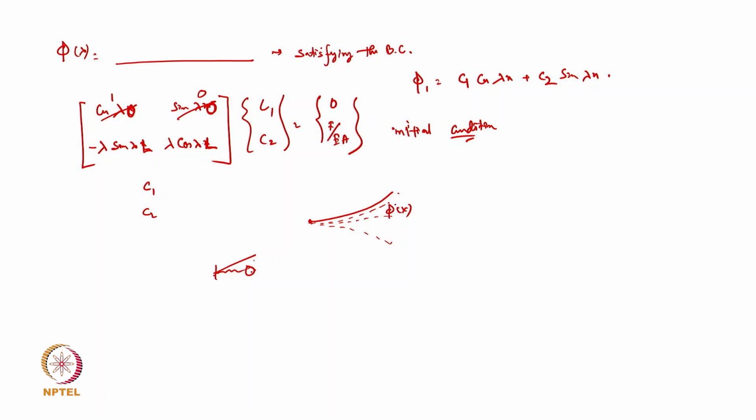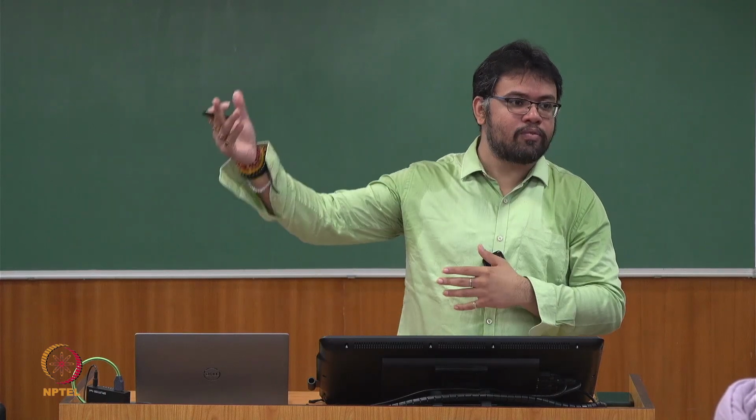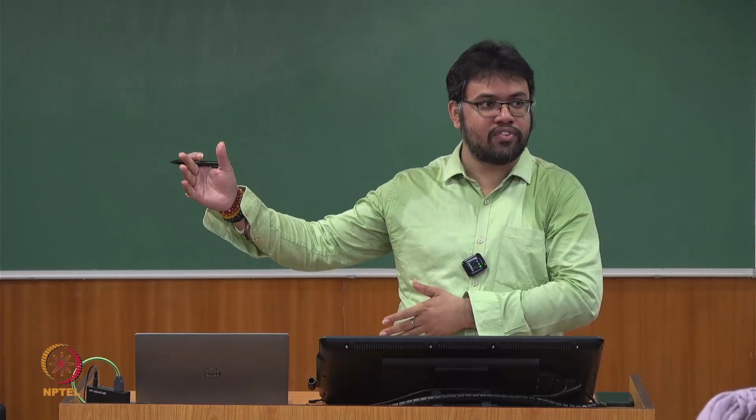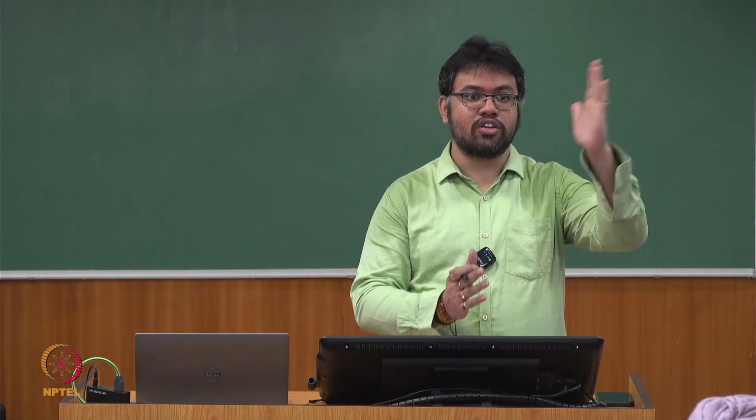But here you have a very rich function made of sine and cosine. So it's like a very high order polynomial, not even a small order, because sine and cosine have almost infinite terms in the polynomial series. So that higher order polynomial you are considering, and you are looking at how the shape is evolving and how the displacement field is changing. You got that idea?